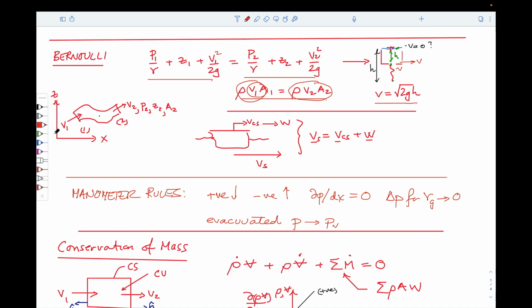And we also need to be cognizant of relative frames of reference. The relative frames of reference mean that if we view from a static location, our static view of what's going on is equal to the velocity of a control volume plus the vector sum of fluid velocity coming out of that moving control volume. So that the addition of these 2 velocities is equal to what a static bystander sees, and that is represented by this expression here.